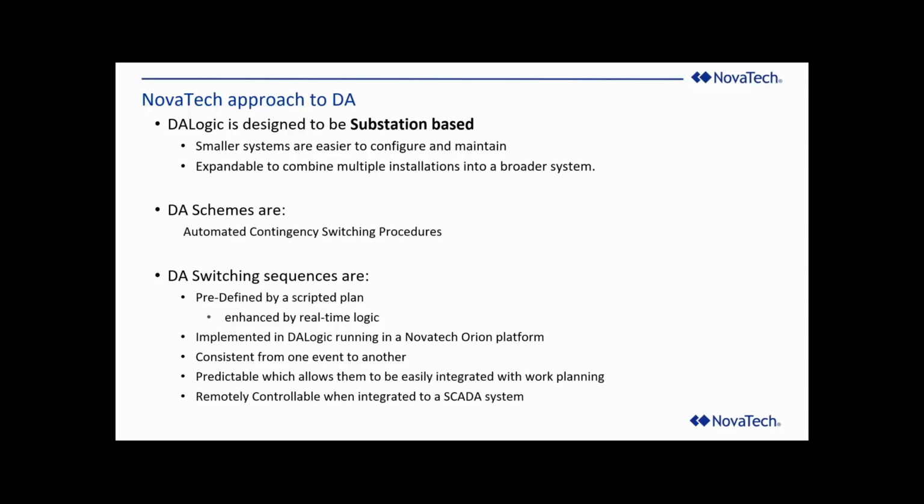It is not intended to be a system that you simply build, these are the devices, go figure it out. There are other DA systems from other manufacturers that intend to do that. Many of the complaints that I hear about those systems is that it is inconsistent for the same kind of a fault. It will switch one day in one direction, and another day for the same fault, it would switch in a different way. That makes operating people in the field very uncomfortable with what is the DA going to do.